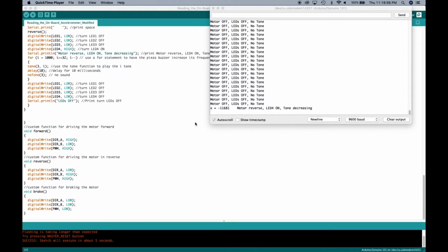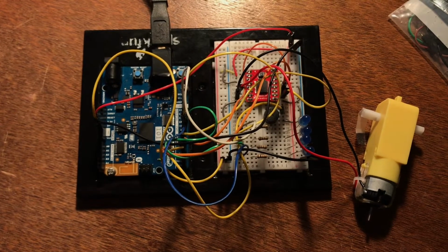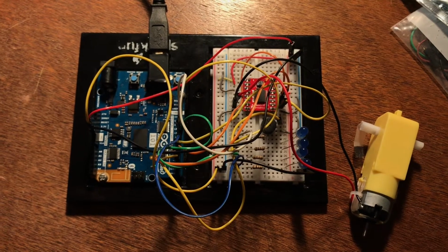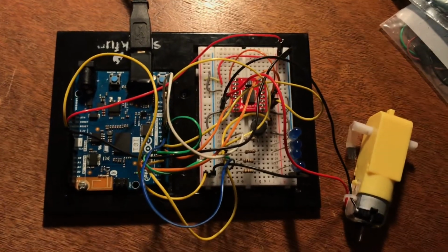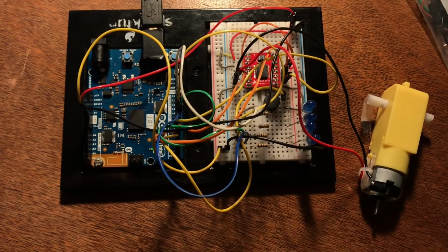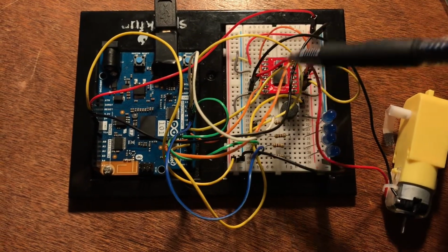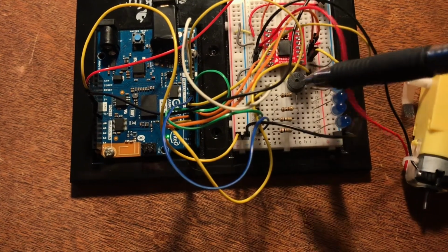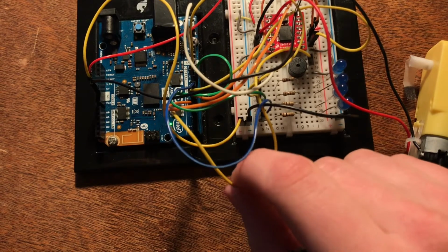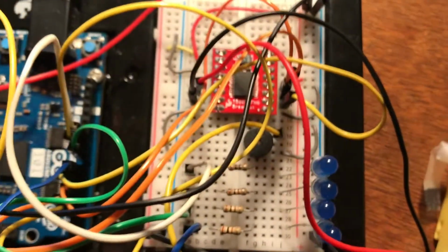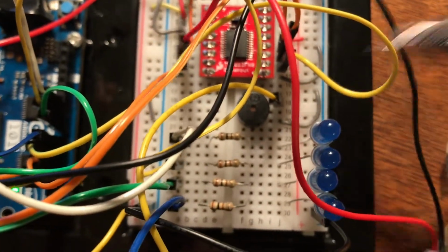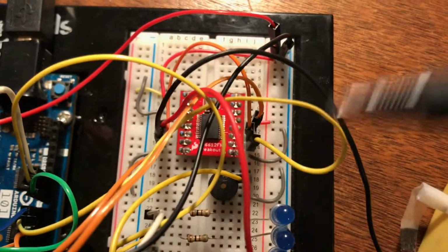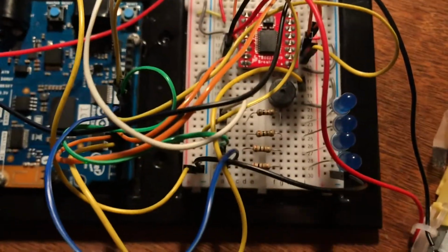This is the modified board for reading the onboard accelerometer. Here we have the accelerometer still hooked up the same way as before, with the same wires and the same pins. But now we've added a potentiometer here. The positive side is connected through this yellow wire to pin number 3 on the Arduino board. It is grounded through its negative side through this gray wire into the negative column of the Arduino board, and then grounded again by this black wire.